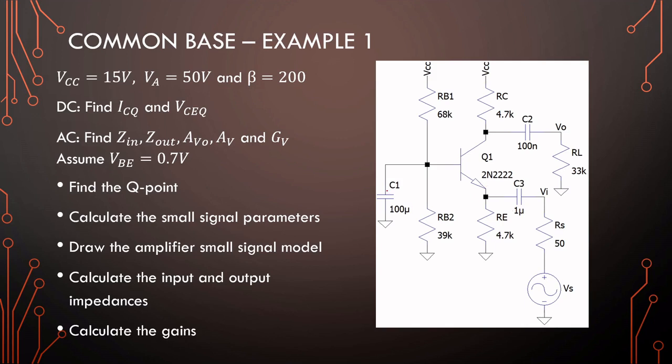Okay, so you will typically see a capacitor here, which if it goes to ground or if it's bypassed and this source is switched off, these two resistors are in parallel with a short circuit. So this terminal right here of a transistor becomes a ground.